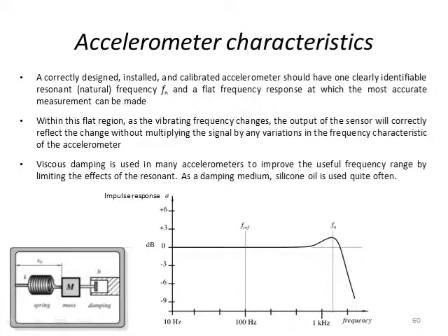So remember when we did our second order transfer function characteristics, we saw this general response, second order system, that was dependent on the damping and the resonant frequency. And the resonant frequency came from K and M. The damping came from B and M.